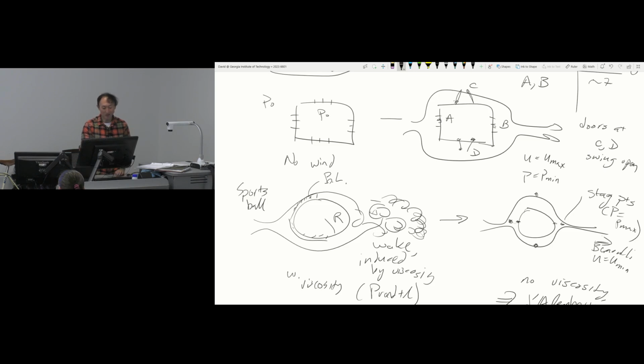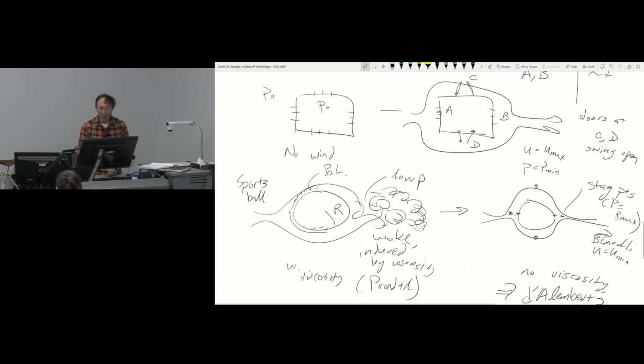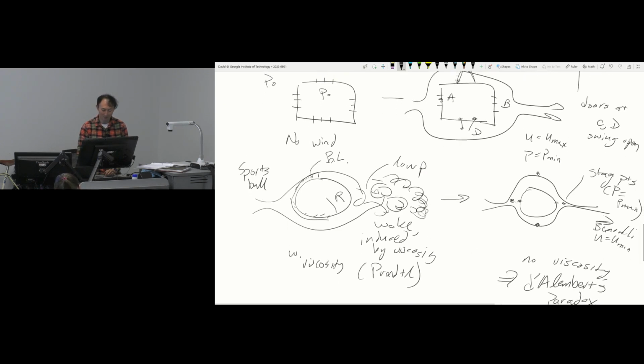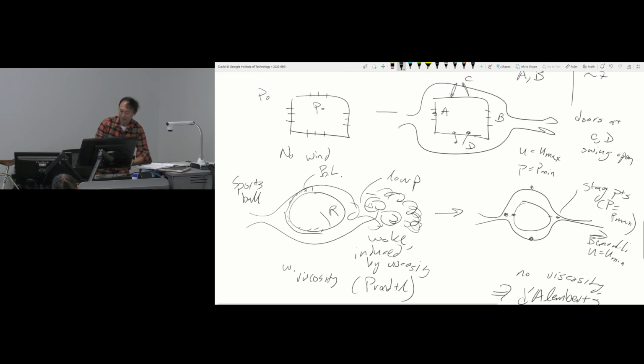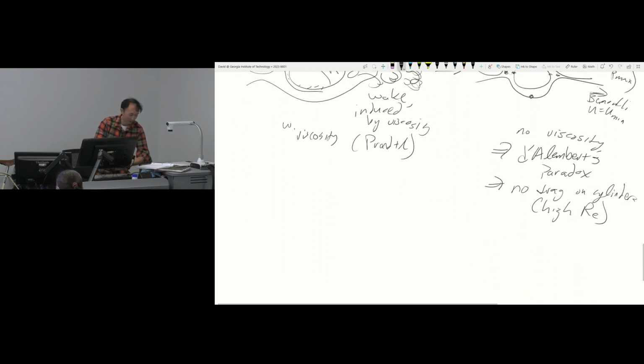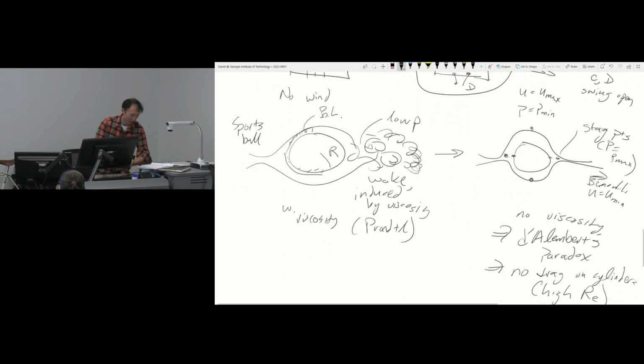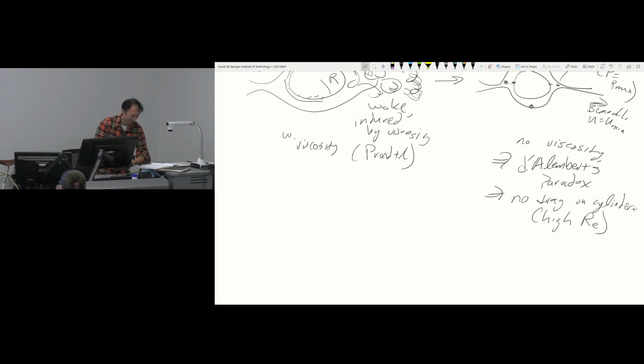And similarly, weird enough, with B, in actual flows with viscosity, you actually have a low pressure zone here, and that actually causes increased induced drag. But you don't have that for no viscosity. You have high pressure on both sides, which is unfortunate. Okay, all right, so that's a little lesson about physically what that does around solid boundaries. And if someone wants to do a course project on that, that's kind of available.